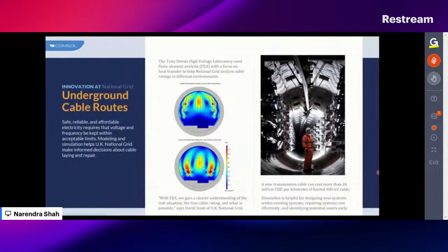In these setups, the close proximity between cables can essentially impede heat losses. It can also lead to a rise in the temperature of the cables and reduce the current carrying capacity of all the coils. In this simulation image, what you see here is the result of a normalized airflow profile within the cross section of the tunnel. So this is a case of both electromagnetics as well as CFD analysis.